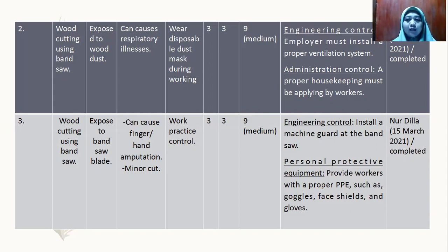ventilation system. For this control measure, the most suitable ventilation system is a local exhaust ventilation system, and this LEV must be provided under the blade slot. To collect dust from the saw teeth, the suction nozzle must be put above the table at the rear of the saw blade.